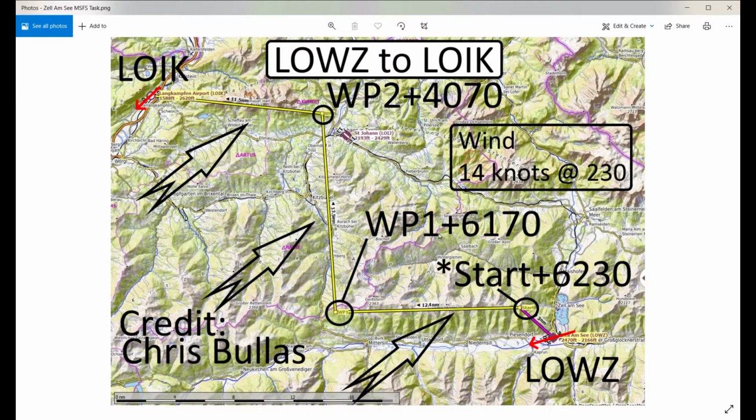If you make the name of the waypoint anything that's got a plus followed by a number, the nav instrument that's in the AS33, and it's going to be in other gliders as well, will interpret that number as you saying this is the elevation of that particular waypoint. There's no other way of doing it in Microsoft flight plans to actually get this elevation read from the flight plan and displayed in the instrument. It's just Microsoft's just not designed for that.